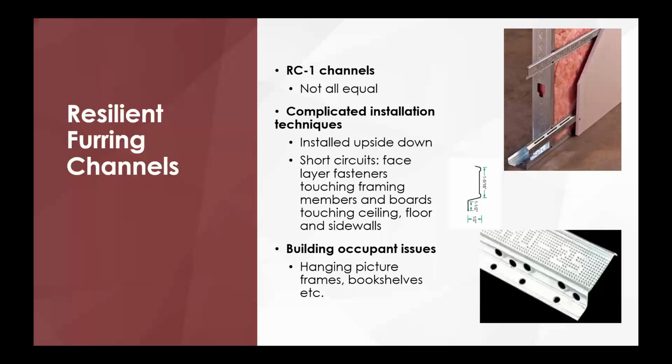Now, something very important to note is that not all resilient channels are the same. You have to read the sound report that goes with it. Also, you have to make sure that you're installing it right. Here are two things to look for. Notice on this first run, my flange is facing down. Every RC added above that, the flange is going to be up.